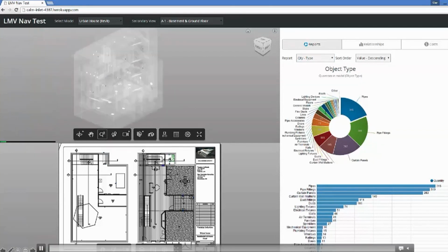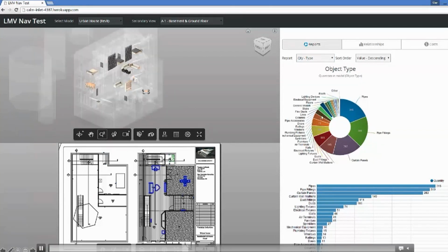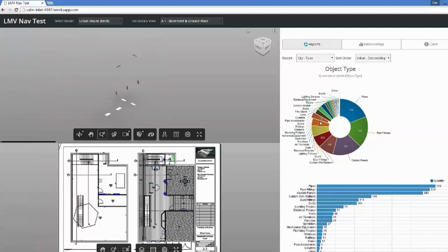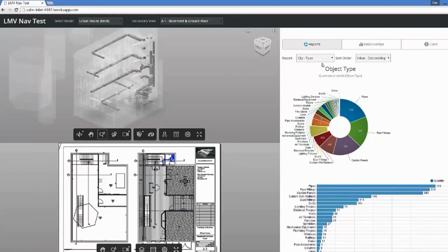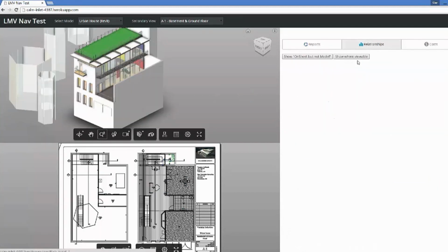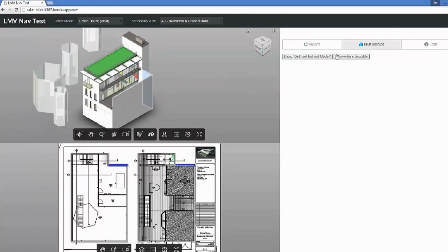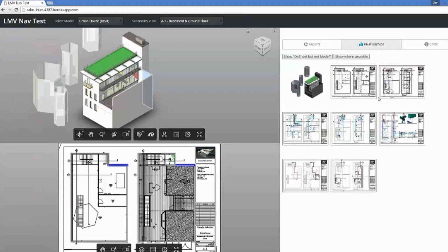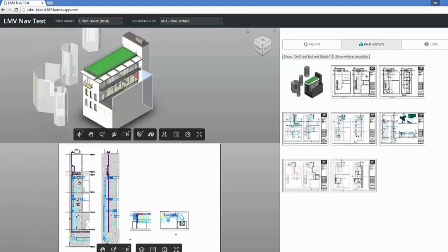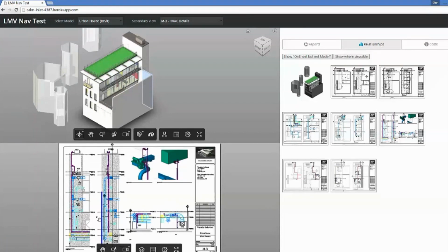So on the right-hand side, you see here we can dig into the pipe system, how many pipes there are, how many fittings there are, etc., etc. So we can start to use the geographic information, as well as the geometry, as well as the actual data that's in the model, to drive and support different processes, be that things like estimated procurement. We've even got examples of people using scenarios like this in the cloud to drive things like pipe cutting, Tiger Stop machines, and things like that.